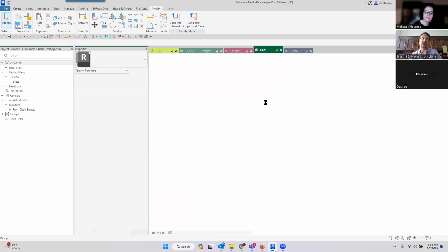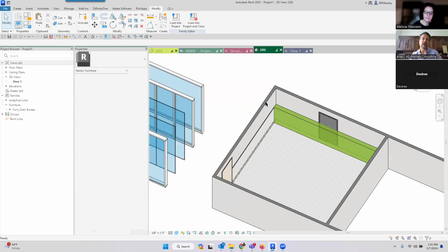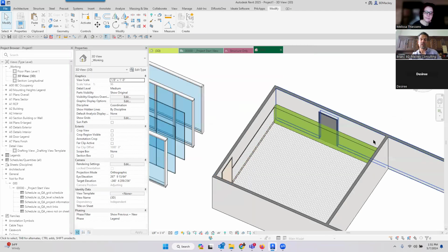There was a new thing that I had noticed, and I thought it was a new 25 thing, but I realized that they've actually been doing this since Revit 23, that they've just made it apparent now that we have the personal accelerator down here in your start bar. I've seen the personal accelerator before, and I thought I knew what it did. But what the personal accelerator does, and I didn't notice this, if you're working on an Autodesk Cloud project, either ACC or BIM 360, when you're not in Revit, it is still downloading your cache. I did not know this until last week.